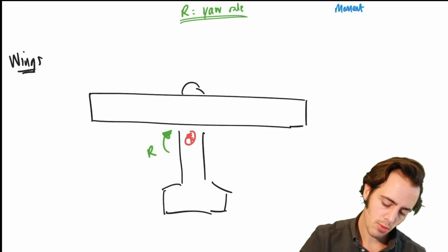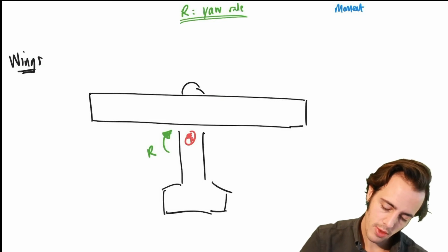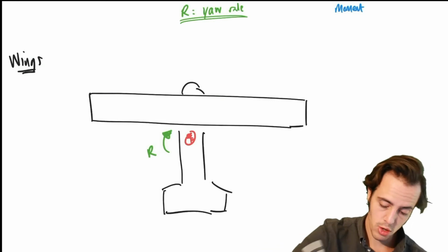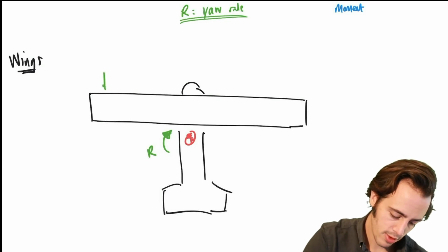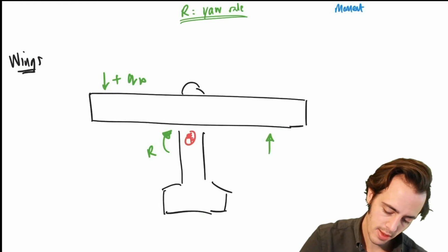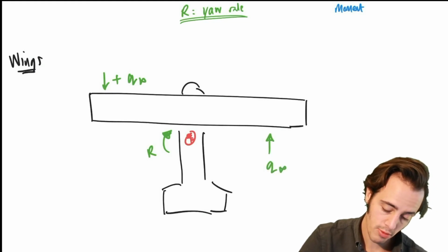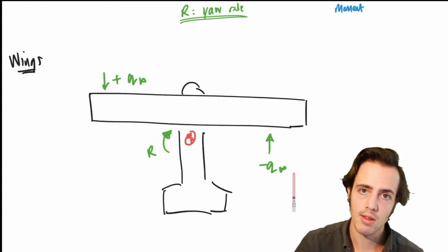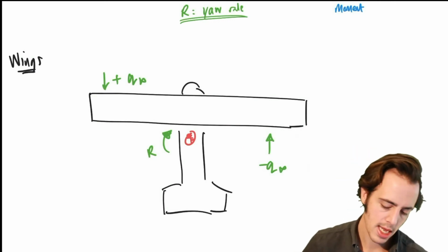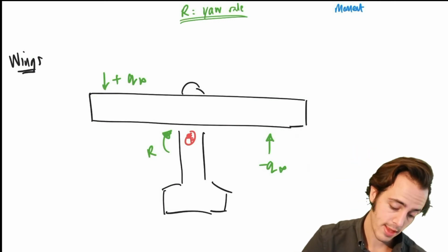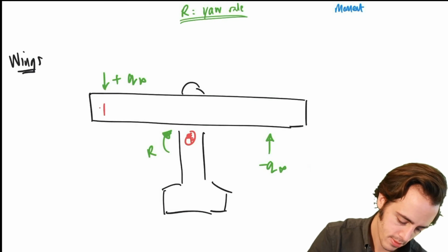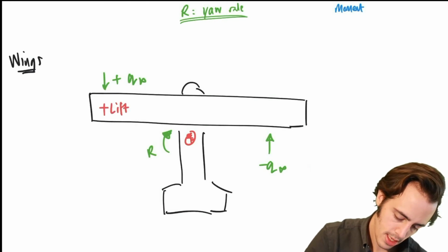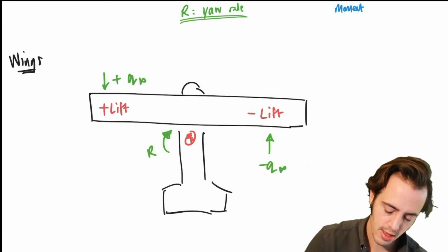So we can think about where this comes from here. If our aircraft is now yawing, we've got an increase in dynamic pressure here, and a decrease here going the wrong way. So effectively the port wing is going faster, and the starboard wing is now going slower. This causes an increase in lift on the port wing and a decrease in lift on the starboard wing.